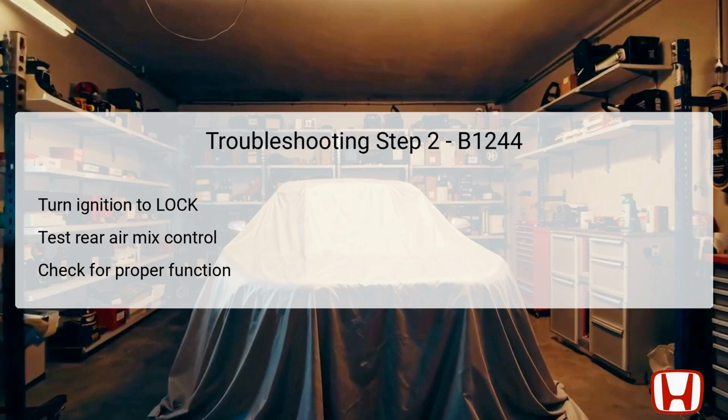This component is essential for proper temperature regulation in the rear cabin, and it should respond appropriately during testing. If the rear air mix control motor is operational, the next steps will proceed without delays. However, should it fail the test, you must replace the rear air mix control motor altogether.